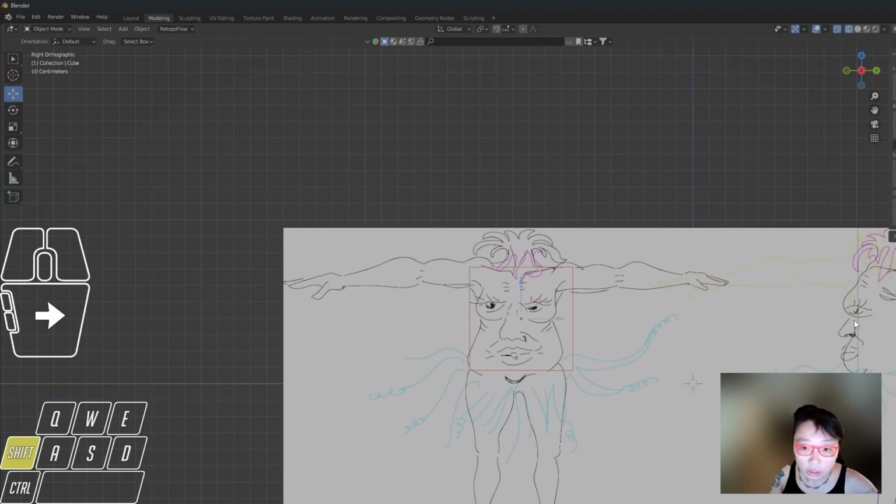Now, in order to add more geometry to it, a really easy, convenient way is to add a modifier. Remember what I was doing before with the cube, adding edges, beveling, extruding. That's a destructive edit. Whatever you're doing, you can't really go back unless you do all the Control Z stuff. But a modifier is a really good way to perform non-destructive edits. So I'll show you.